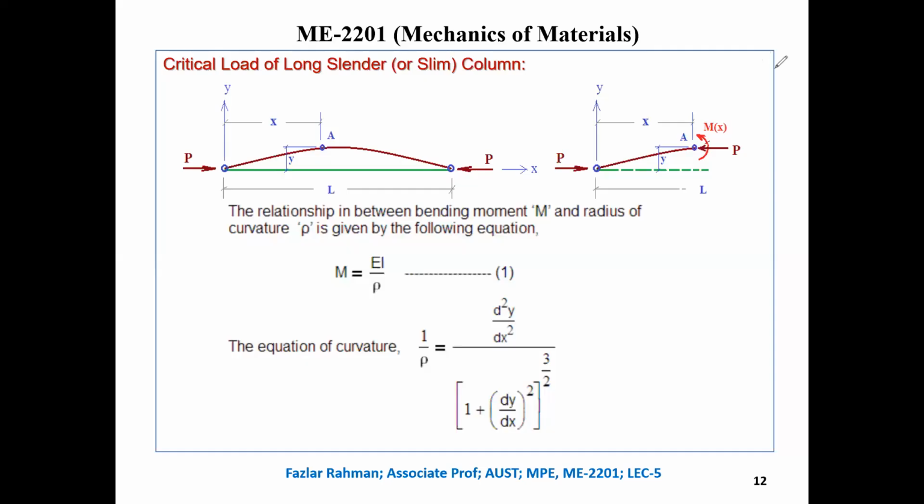So that's why it is bending in the beam, because at every point there is a bending moment working. Similarly, in the column, I showed in the figure that it is bending in the upward direction, right? It might bend in the downward direction. It depends. Anyway, it can bend. Why is it bending then? Because you are applying load at two ends parallel to the axis, but at each point there is a bending moment. That's why it is bending.